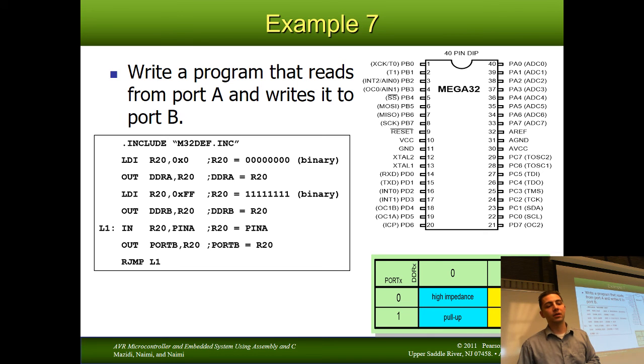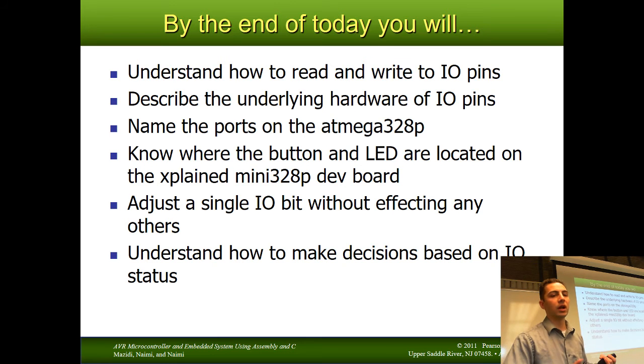Okay. At the beginning of class, I promised that by the end of this, you were going to understand how to read and write to I/O pins. Describe the underlying hardware of the I/O pins. The underlying hardware of the I/O pins, by the way, is just a register, a flip-flop, okay? Name the ports on the 328P. Quiz. What ports are on the 328P?